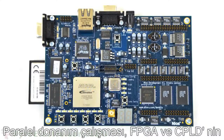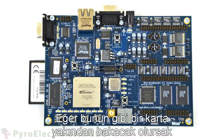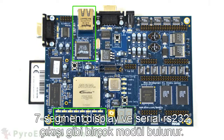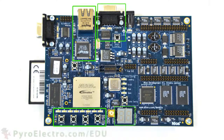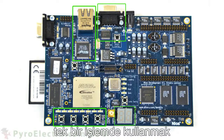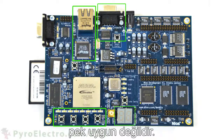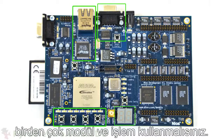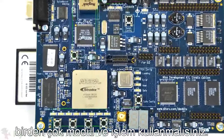Parallel hardware operation is a key element of FPGA and CPLD. If we look at a board like this one, there are many modules like Ethernet, push buttons and LEDs, 7-segment displays, and serial RS-232 output. It's not feasible to control and use all these different input and output devices with a single process. You need to use multiple modules and processes to control and interpret the data they send and receive.